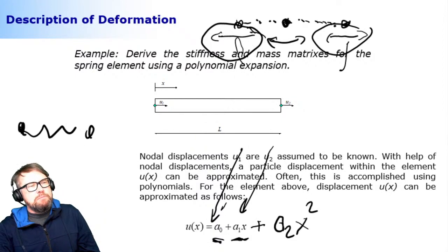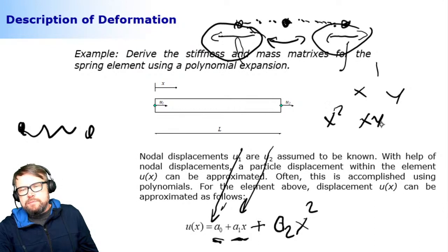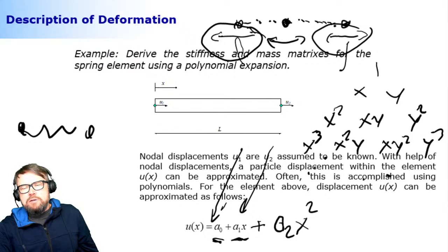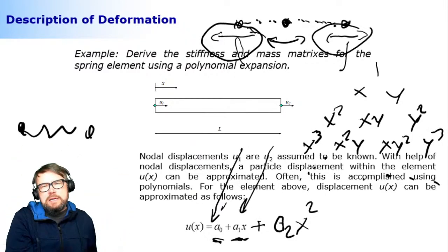They actually come from the Pascal's triangle, which we can take a look at a bit later. But shortly, the Pascal's triangle is something that has a component like this. So xy, this is a planar case, I mean two-dimensional case. x power 2. You can use this kind of polynomial selection when you're building a shape function for, let's say, a plate element. And so on and so on. This goes as far as you want, so there is no limitation. This one is called Pascal's triangle.